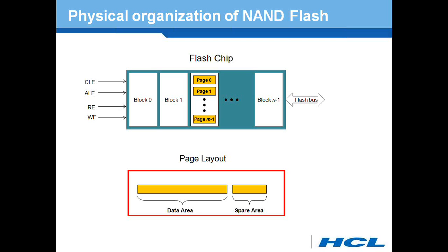So coming back to flash memory, as I mentioned, this memory array is made up of a finite number of blocks. At the time of manufacturing, there could be some initial invalid blocks. The flash which has invalid blocks will work similar to a flash with all valid blocks. Only this invalid block information needs to be stored before doing any read or write operations.